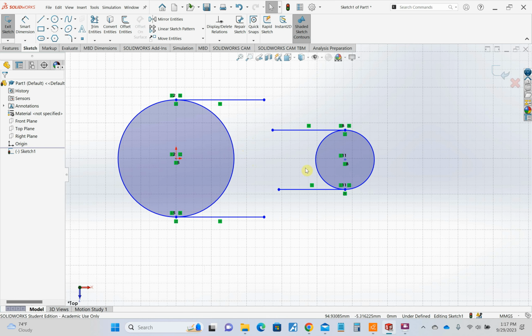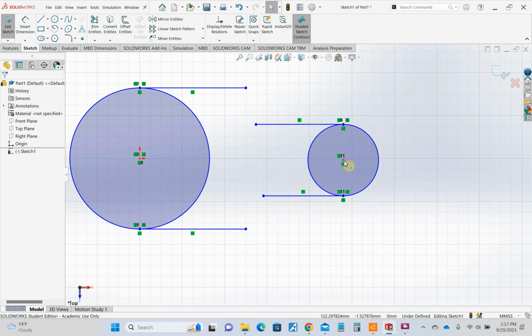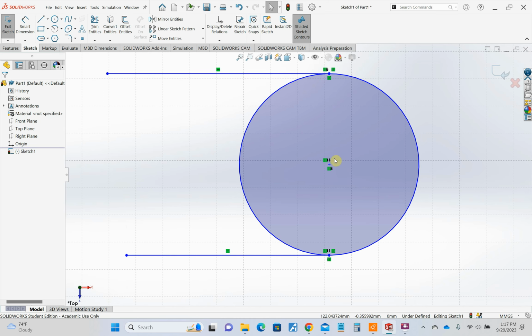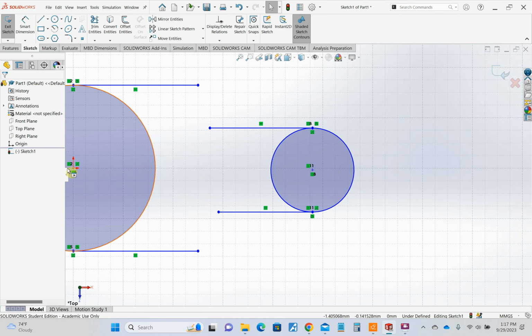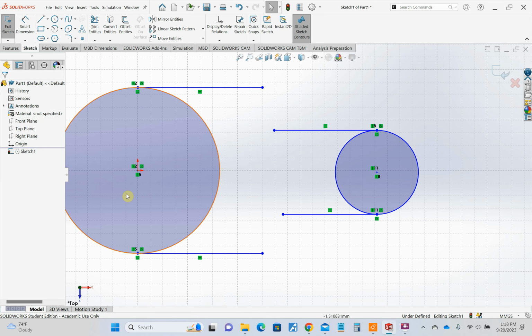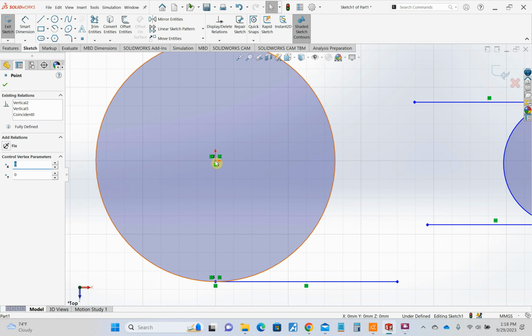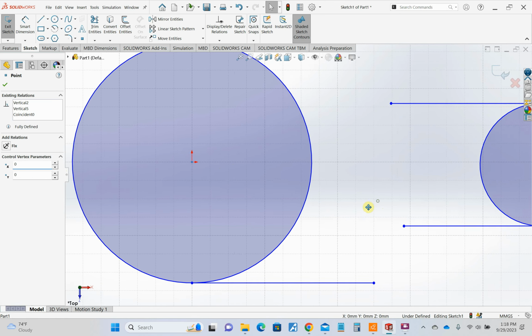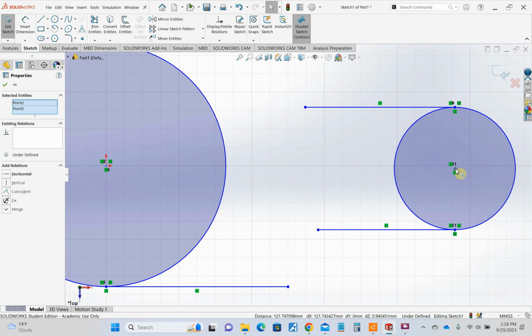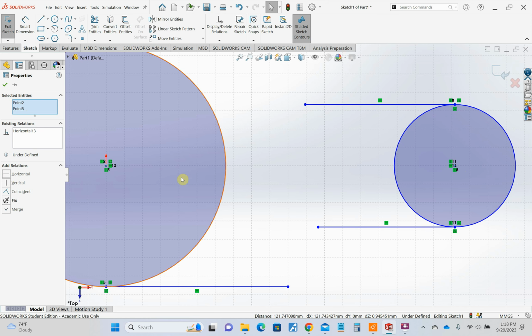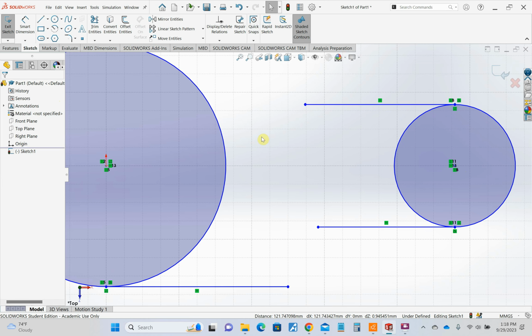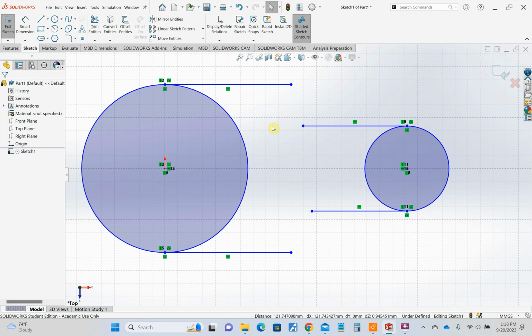Okay, so I'm going to make sure that these are on the same horizontal, and it doesn't look like they are. See, that's a little bit lower than that line there, which is lined up with the origin point. So I'm going to select both points. I pick on that origin point, and then I hold the control key down and pick on this point. It'll just narrow those two that I selected, point 2 and point 5, and I'll put them on horizontal. If you watch that, that should pop up as it did right there. Now they're locked in on each other.